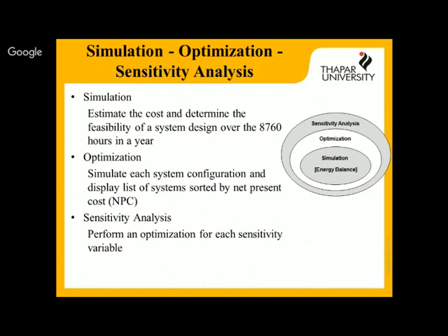Suppose in this system, PV plus DG only is a better choice. We don't need a large battery backup. Whenever PV is not there, I'm going to operate the diesel system. So it may be an economical system. DG plus battery may be one of the economical options. So it simulates all possible combinations, and according to the cost of each combination, it finally gives you the results that this is the best system.